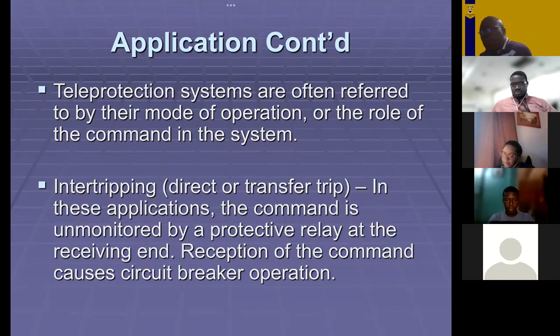So if you intend on using a direct transfer scheme, then you have to give careful consideration to the type of medium that you're going to use to convey that information. If it is susceptible to noise, then you recognize that the intertrip scheme would not necessarily be the one that you would want to institute.